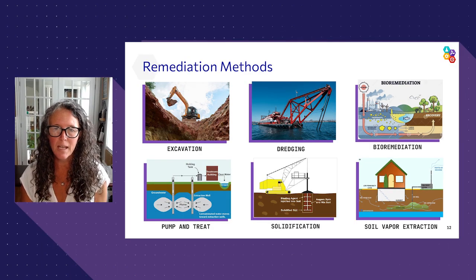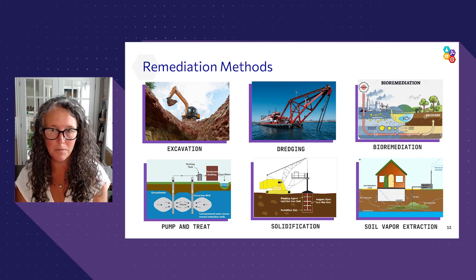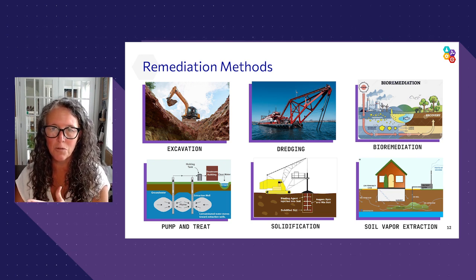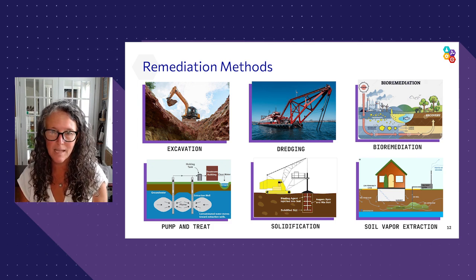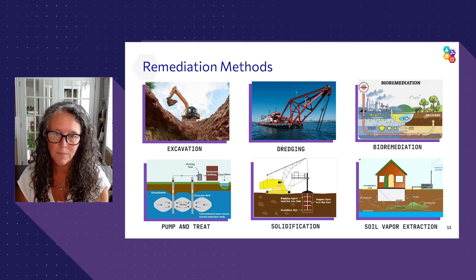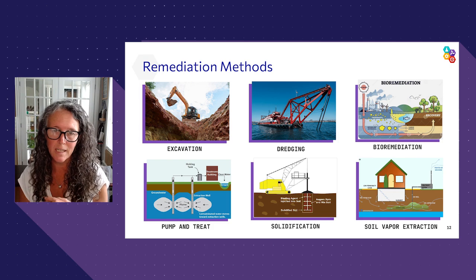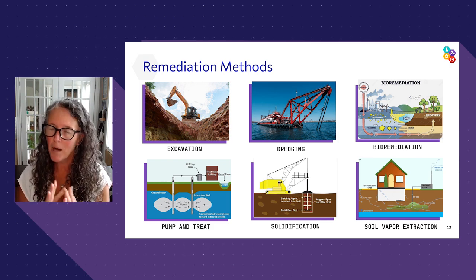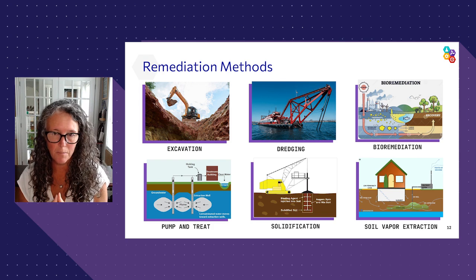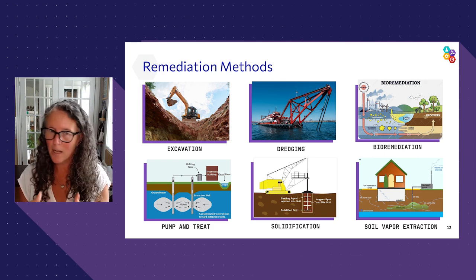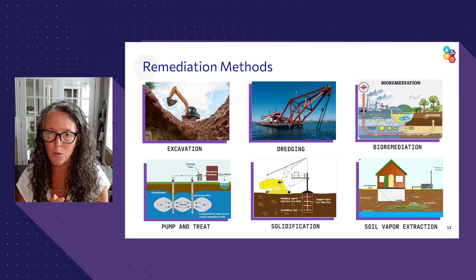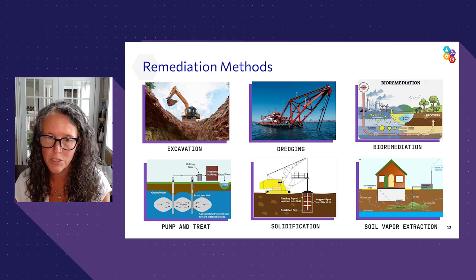And so typically you're taking it from an area where it has a receptor to an area where it doesn't have. So maybe you take it out of the ground and then you take it to a land farm that has a lot of containment and it can be properly treated. It's a very rudimentary technique, but it is very effective and also very popular. It's primarily going to work for things like hydrocarbons, so the fuel spills, but it's not going to work with some of your more persistent chemicals that are going to require much more complicated remediation technologies.